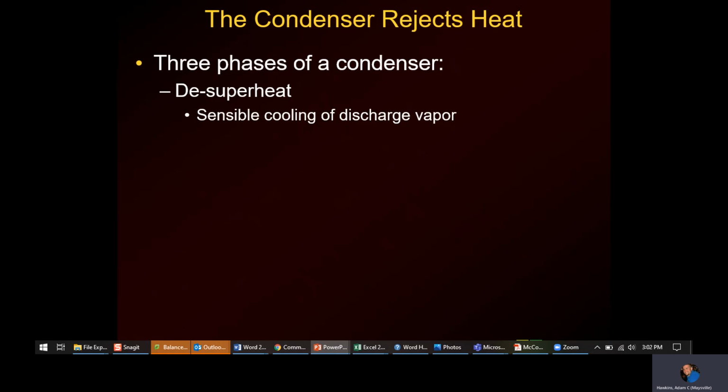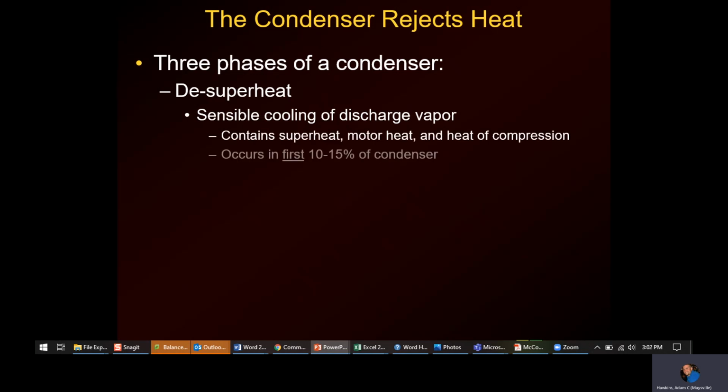Your compressor magnifies that, and then your condenser has to deal with it. So if you have higher than normal superheat coming into the compressor, then you're going to have higher than normal discharge superheat, and you're going to have to get rid of all that through the desuperheating process before you can ever start to condense. On a high temp day outside, when it's needing all of that anyway, you may struggle, because now you've got more heat to get rid of than you need. So it keeps your efficiency down if you can keep those numbers in check.